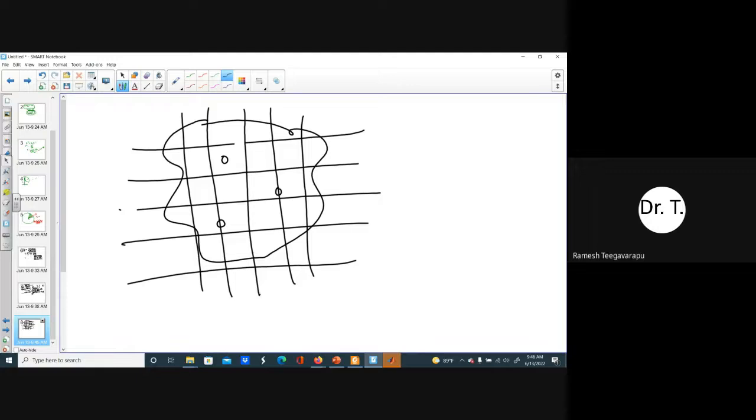Radar data provides spatial variability of the rainfall, which cannot be provided by rain gauges because rain gauges are point measurements. Rain gauges sometimes miss extreme values because they might malfunction in case of extreme winds or extreme rainfall. So there's a possibility that the rain gauge is knocked out because of extreme rainfall events, and we might miss extremes in that case. And the other issue is that